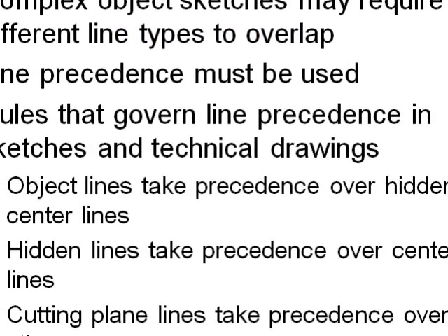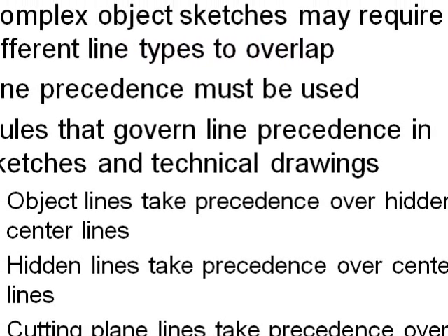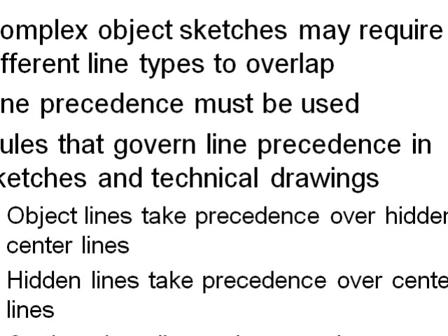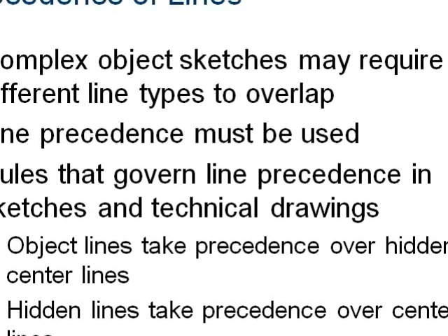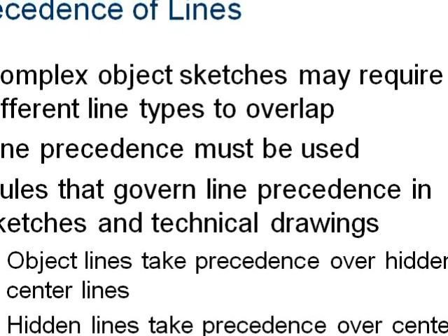Some lines have precedence over others. Object lines should be shown over hidden and center lines. Hidden lines should be shown over center lines. Cutting plane lines should be shown over all others.